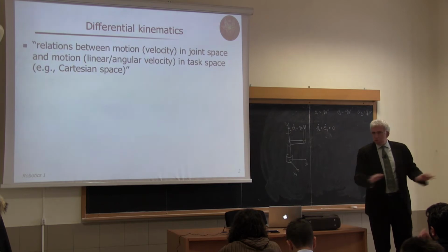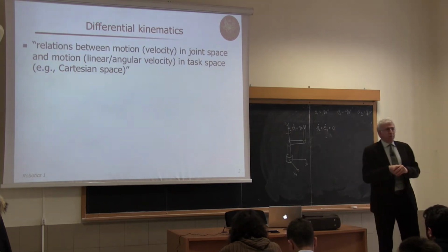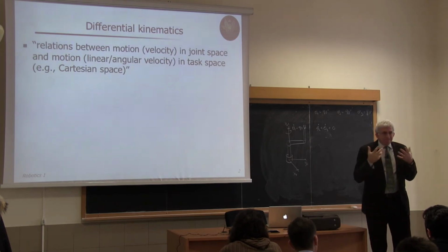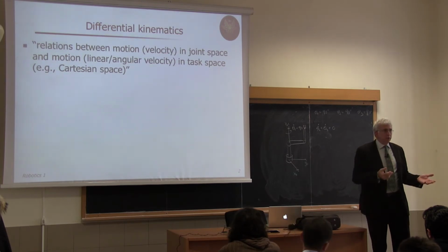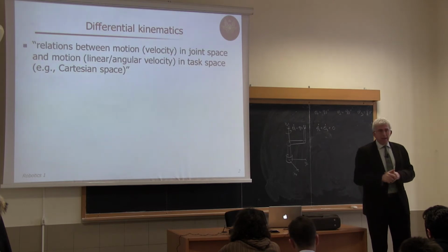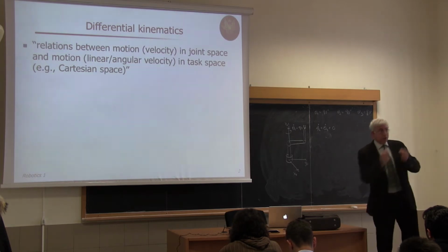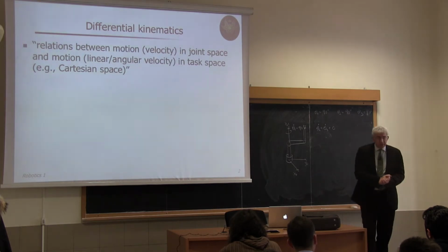We have one solution. If everything is correct, no special problem. While the inverse kinematic problem was finding a solution to a set of nonlinear equations. We may find it in closed form, or we need to resort to a numerical iterative algorithm and so on. So it's a synthesis problem. We have to find some configuration that realizes a specified pose for the end effector.